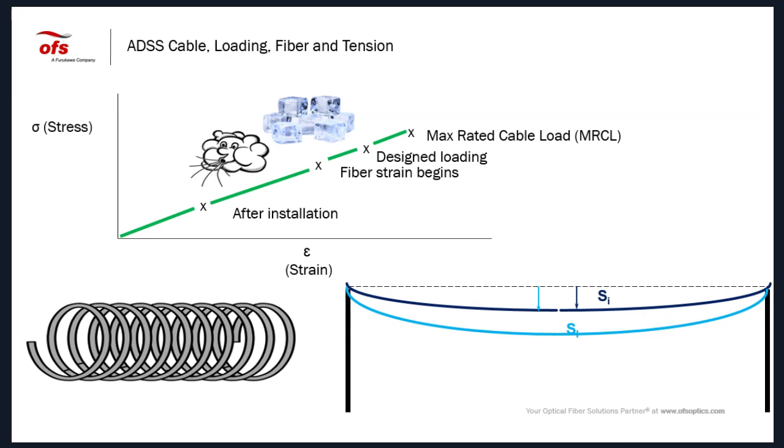If we exceed this parameter, that is very important, the cable can break. But if we are in this green zone, we are safe. The cable here is acting like a spring. So this is how the ADSS cable is operating in the field.